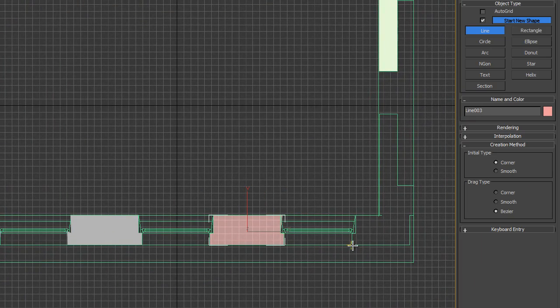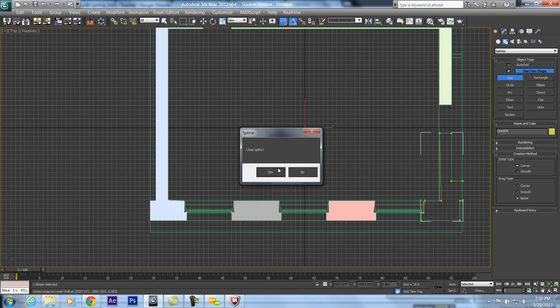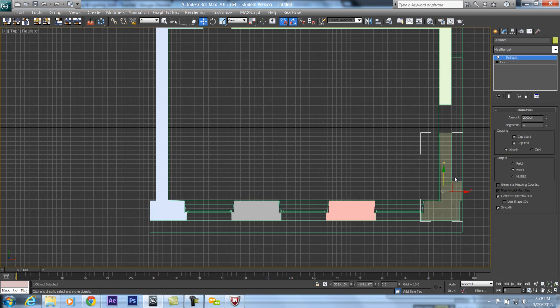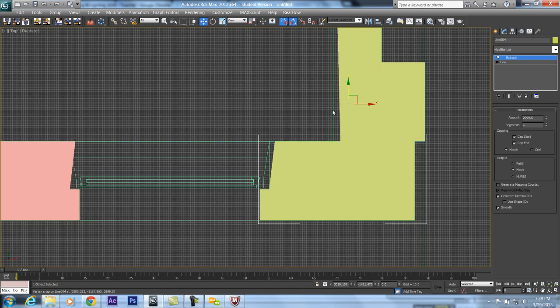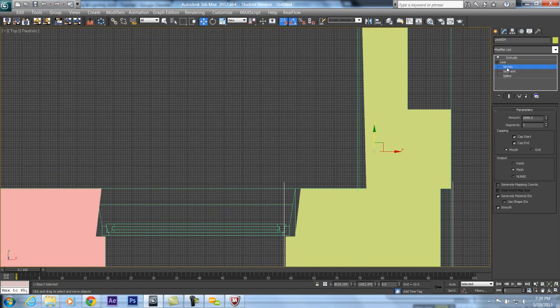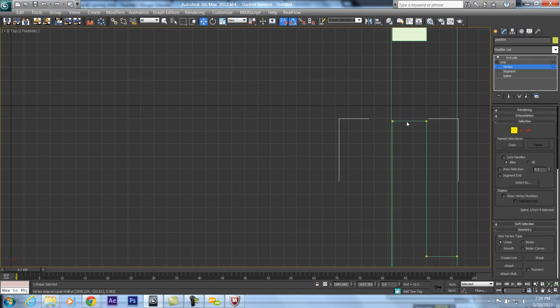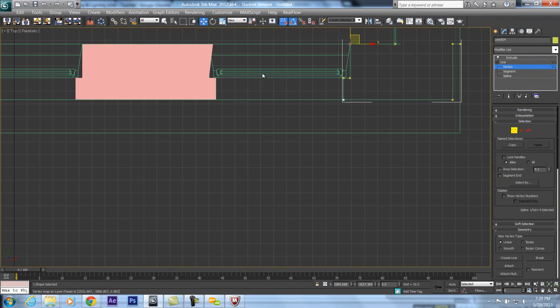I don't really recommend that you clean the DWG files and do the modeling from those files, simply because they can create bugs in the future, and stuff like that you really want to avoid. Now, as you see here, I didn't model it very well, so I can always go and fix those vertices to match my DWG drawing perfectly. Okay.